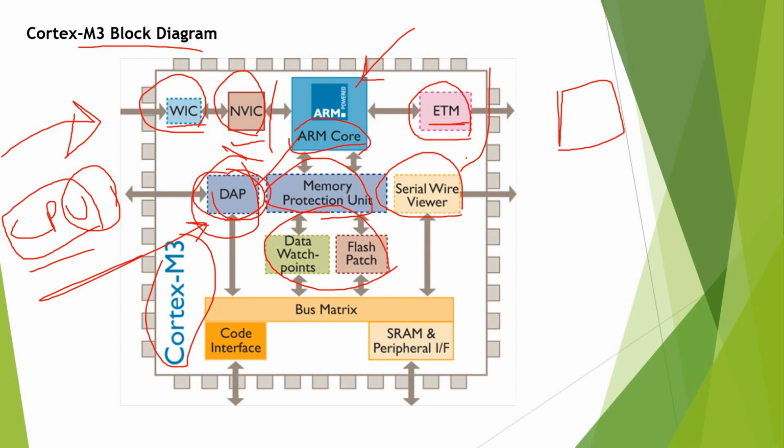This is why ARM offers this option through the serial wire viewer. So we have the possibility to, for instance, do some one-way streaming from the Cortex-M chip to the host machine. We can even establish communication through this channel without the need for a proper communication interface like UART, SPI, and many other peripherals outside the CPU blocks. Of course, we'll discuss this in detail within the debugging and tracing lectures.